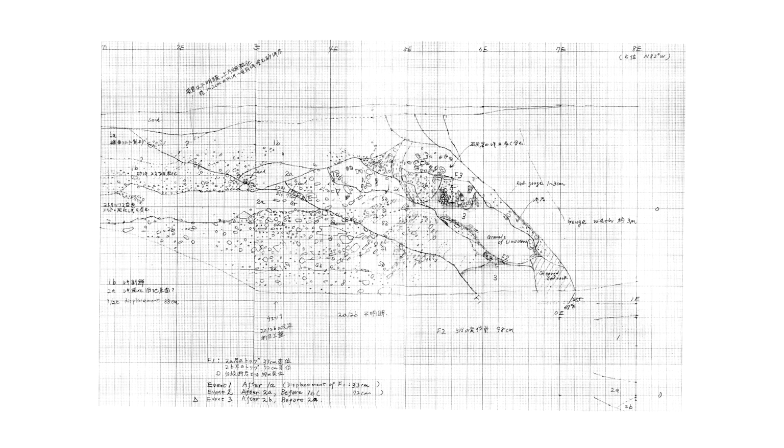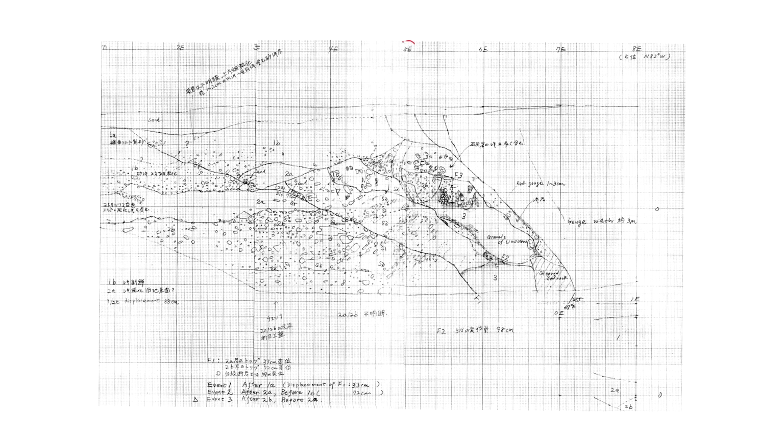This is on the graph sheet. As I told, we put the grid one by one depending on how deep the trench is, or what the height of your trench is. Usually we are comfortable putting a grid of 1 meter by 1 meter. And then you have to number these grids.